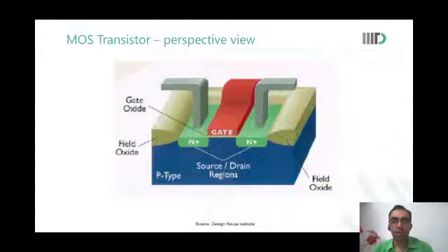Okay. So yes, Meher? Yeah, I mean, adding to Madhur's point, I didn't understand that if there can be a capacitance between your source and your substrate, because of the same reason, due to the existence of a depletion region, then why can't there be a capacitance between your inversion layer, which is electron rich, and the substrate, which have different dopings? There is a depletion junction in between them.